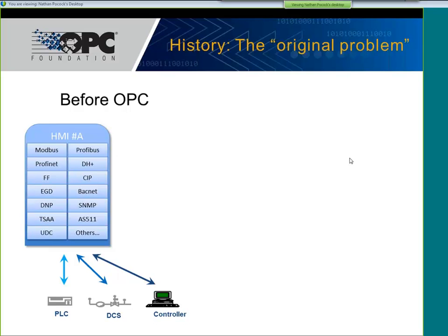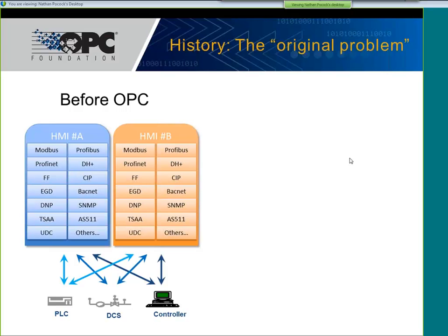So let's take a little look at life before OPC and understand why OPC came into place in the beginning. I'm sure a few of you on this call will remember the days before OPC and the problem that everybody had, where they were a prisoner of their own technology. On the bottom of the screen you can see various different controllers, and at the time each HMI or client application had to have an extensive library of plugins or drivers for different protocol implementations. So you might have Modbus, Profibus, Data Highway, various different protocols. And the difficulty was that all the other guys had to do the same thing.